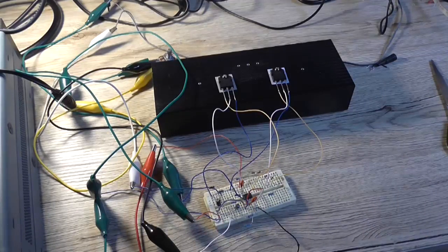So be sure to use at least 1 watt devices. But anyway, it's working. It works reasonably well. It sounds alright, yes. As an amplifier to drive a speaker, no, not so much. But it'd probably make a very good Class AB headphone amplifier. The only thing is it has a fairly high quiescent current draw of around 60 mA.